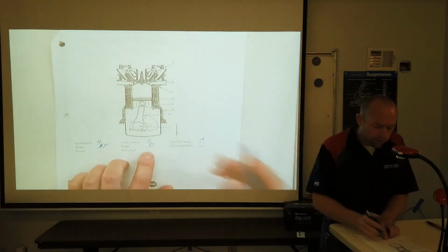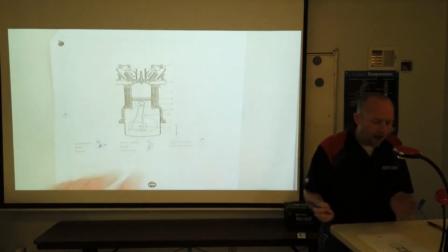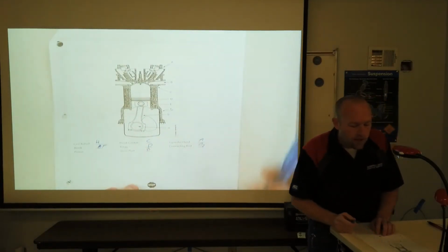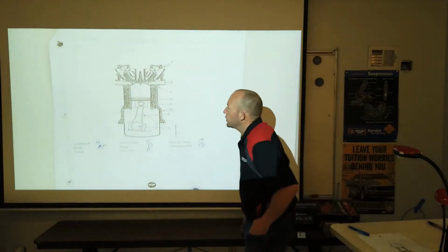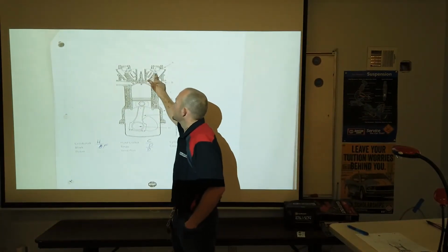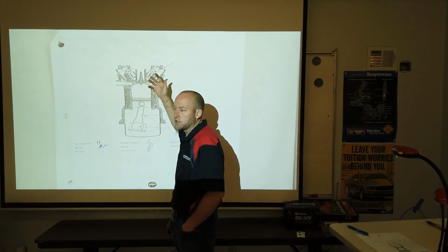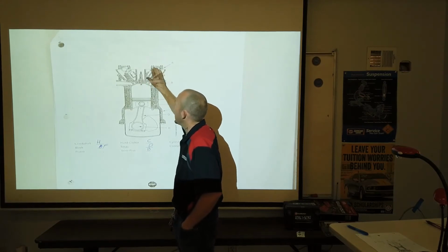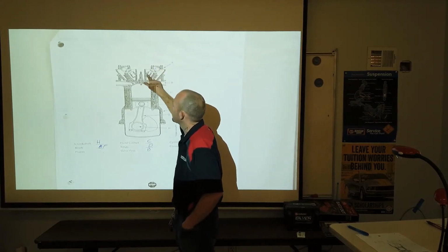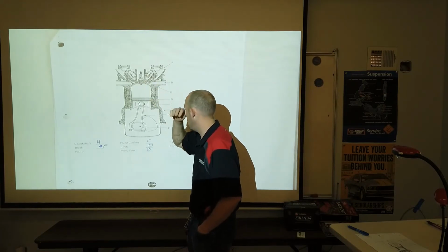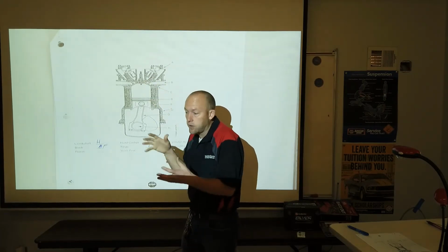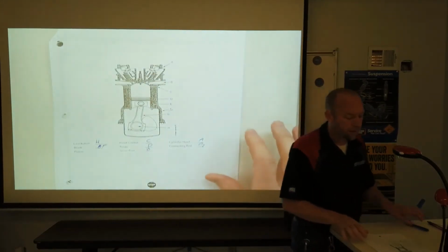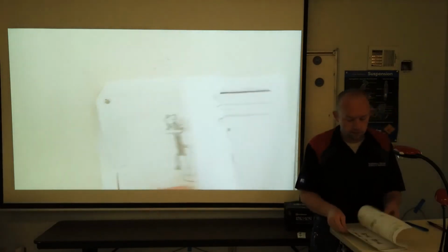Then our port would be B, the valve port there. The connecting rod is G. A couple of things that I wanted to point out to you on this overhead design. This is not a rocker. This we would typically refer to as a follower. It kind of serves the job of a rocker, but it's an intermediate in between the cam lobe and our valve. This would be a little lifter off to the side there to help maintain proper clearance and tension so that we don't have parts that can rattle around. But we would typically refer to that as a follower on this overhead design.